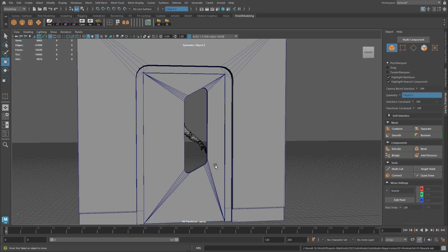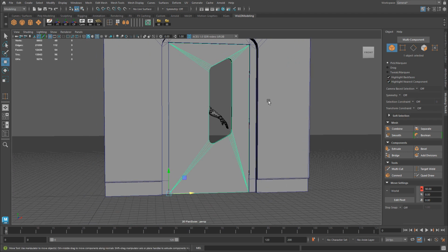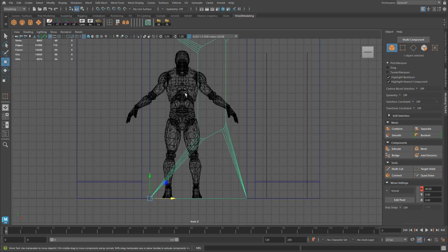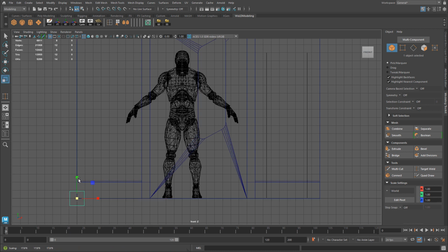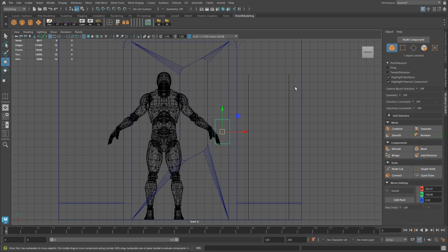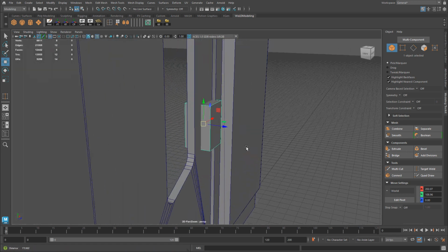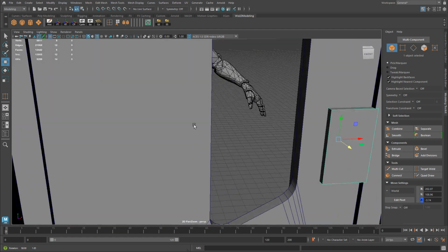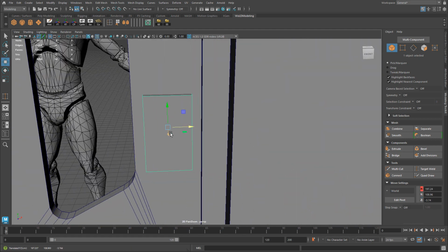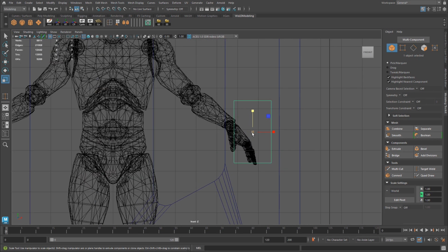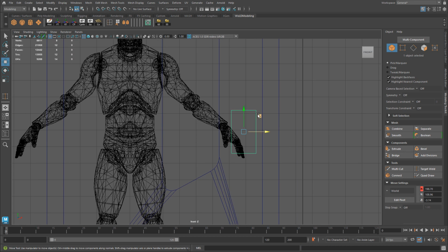Let's create the keypad area and the door handle. I'm gonna disable symmetry. Let's go to front view, and I'm gonna create a cube. This is gonna be our keypad section. And let's just position it where it needs to be, right by here. And let's get it inside closer, like so. Let's make it smaller, right about there. Basically, we just resize it based on the human reference scale you have inside the scene.